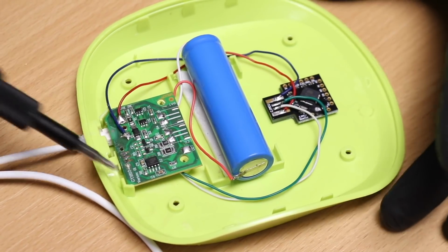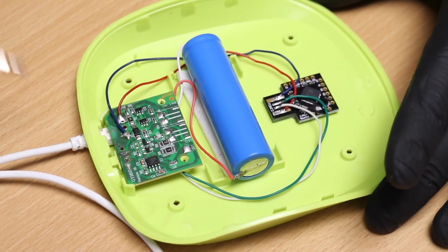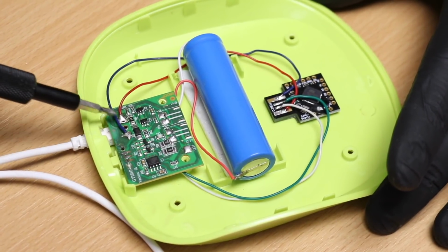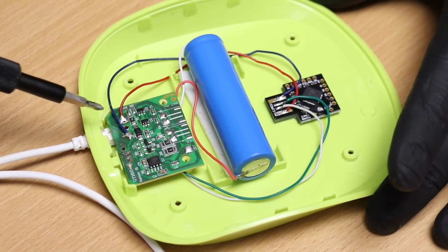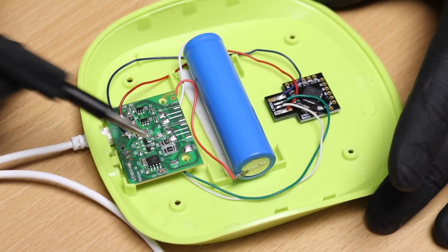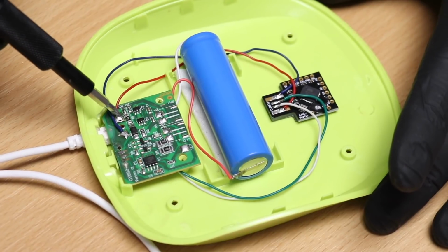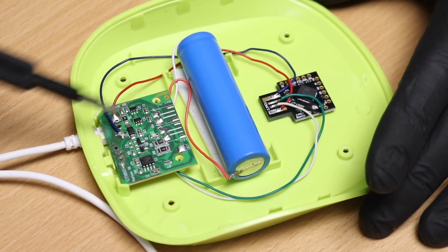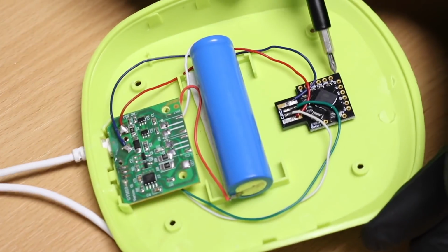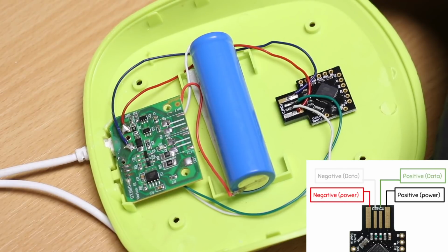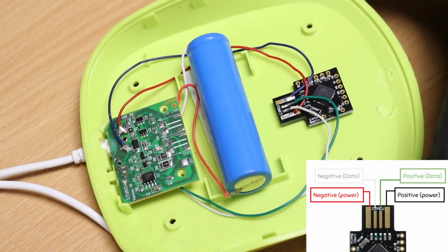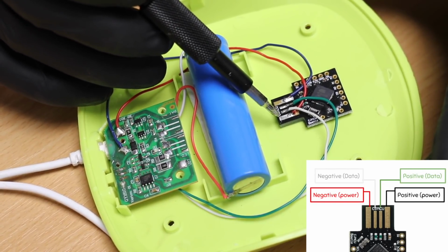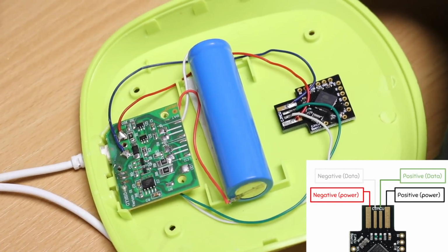Okay, so this is the main board that was shipped with the lamp. These two solder points here, this is the negative point, this is the plus 5 volt wire that we can solder onto. So that's the power? Yeah, this here, the red one is the power, the blue one, I should have used black, but there wasn't any black handy, is the ground. Here's the Arduino board with the ATmega32U4 chip and the 4 connections that we made, which are ground, data plus, data minus, and positive 5 volts.